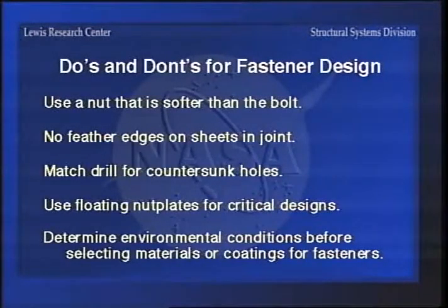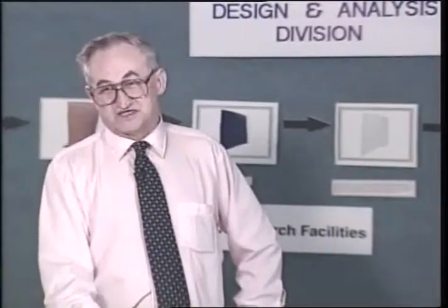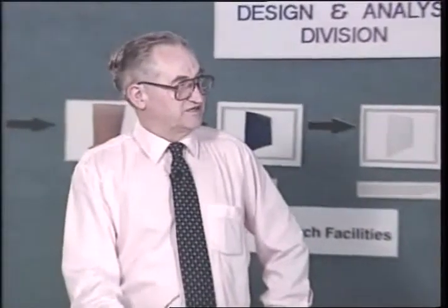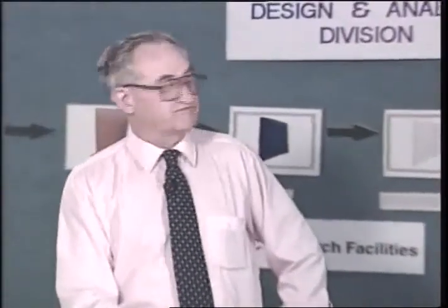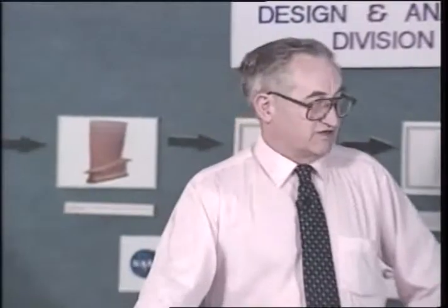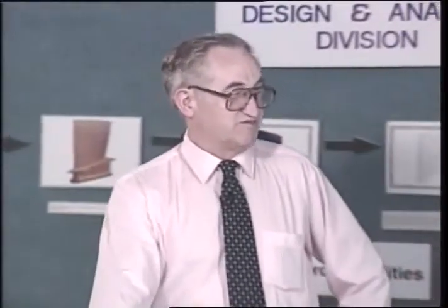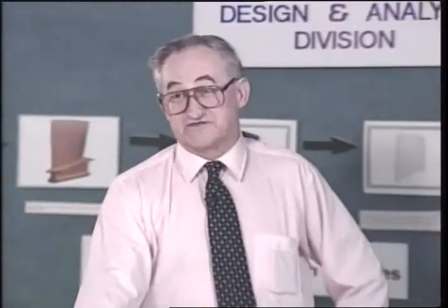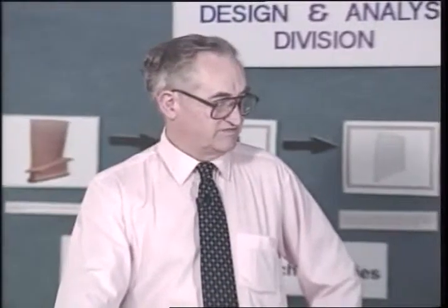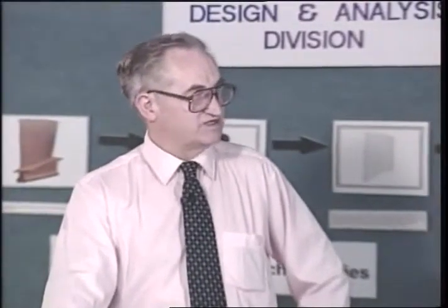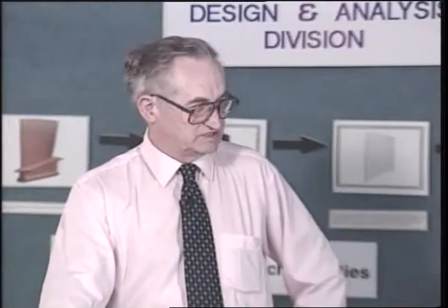Match drill for countersunk holes. Use floating nut plates for critical designs, particularly for countersunk fasteners, so that the countersink can center the fastener and the nut plate will not be trying to bend it. Determine the environmental conditions before selecting materials or coatings for fasteners, because you want to make sure that you're covered with your temperature range.